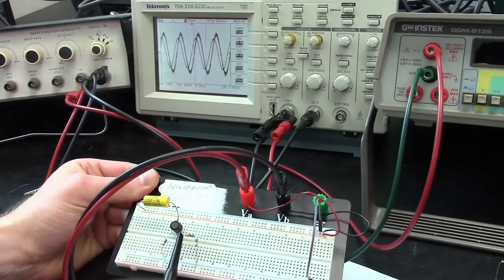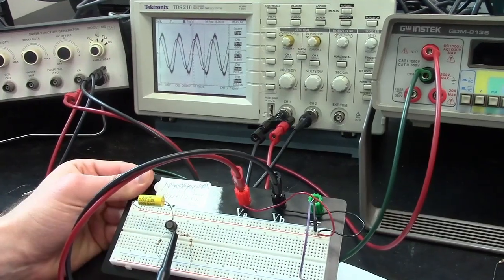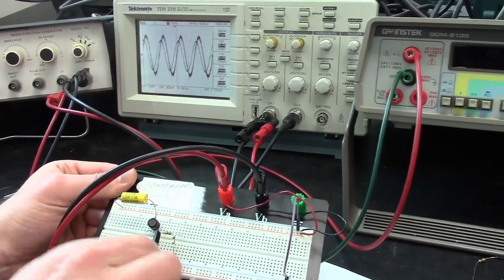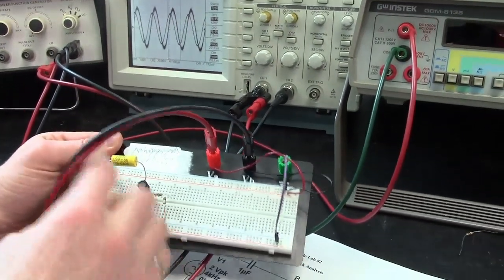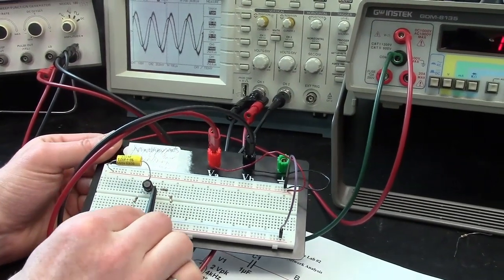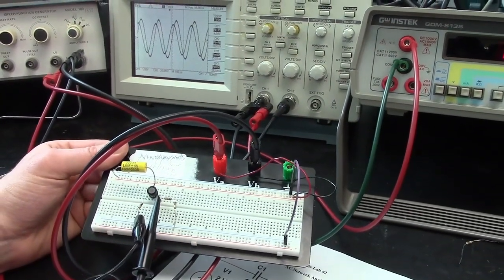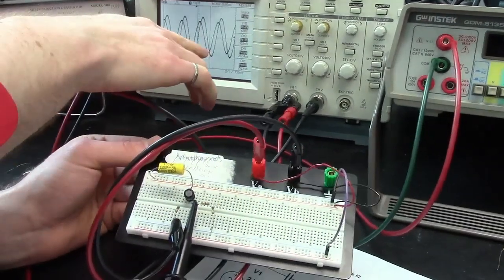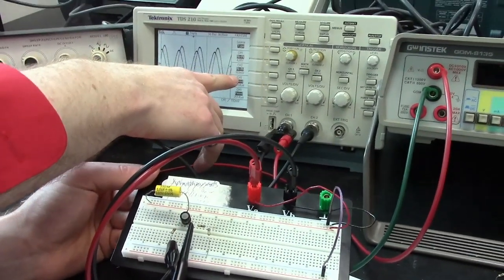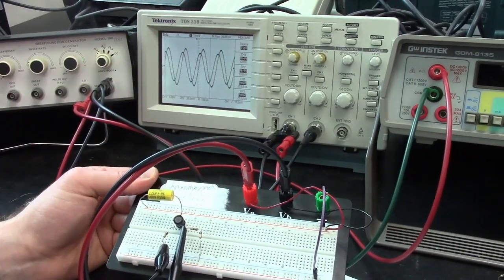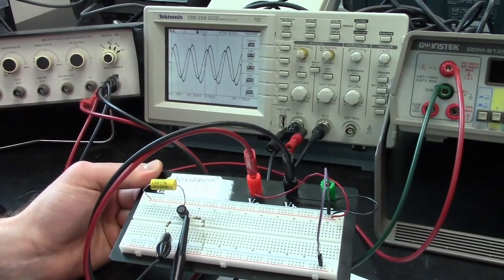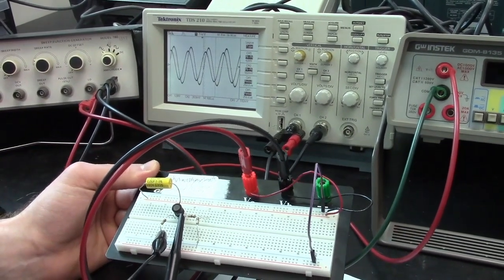So we can see that for this small signal, very noisy measurement when we connect this ground to the ground on the breadboard here. Watch the noisiness of that signal cut down, and that's a lot cleaner there. So we can get a much better measurement. In fact, it turns out that the peak to peak is lower than we were measuring before, and that just changed by cutting down the noise by connecting the ground cable there.